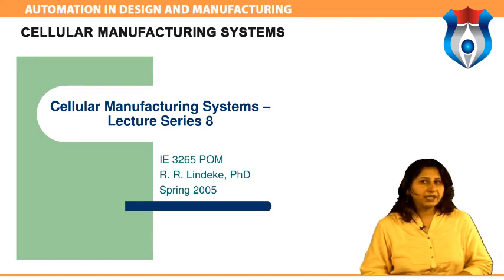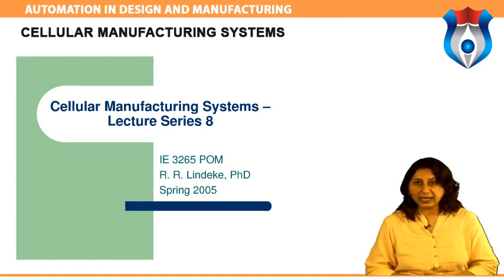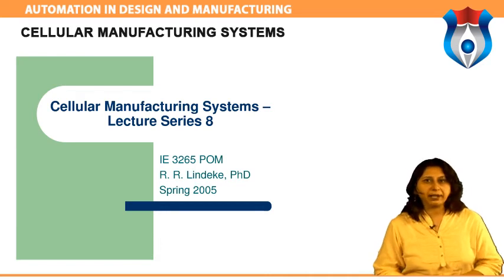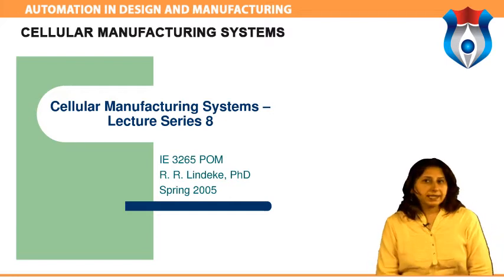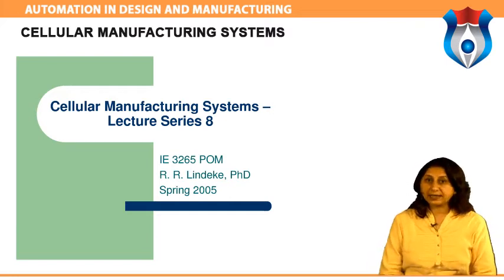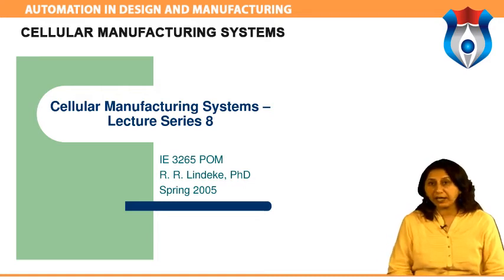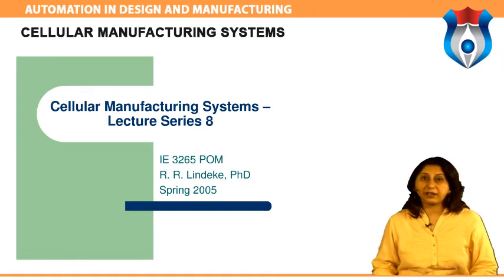It is, in a sense, a self-contained mini production line that caters to a group of products that undergo the same production process. Cellular manufacturing involves the use of work cells, which is how it got its name. Since differently processed products need different work cells, a large company with diversified products needs to build several different work cells if single process flows are desired.